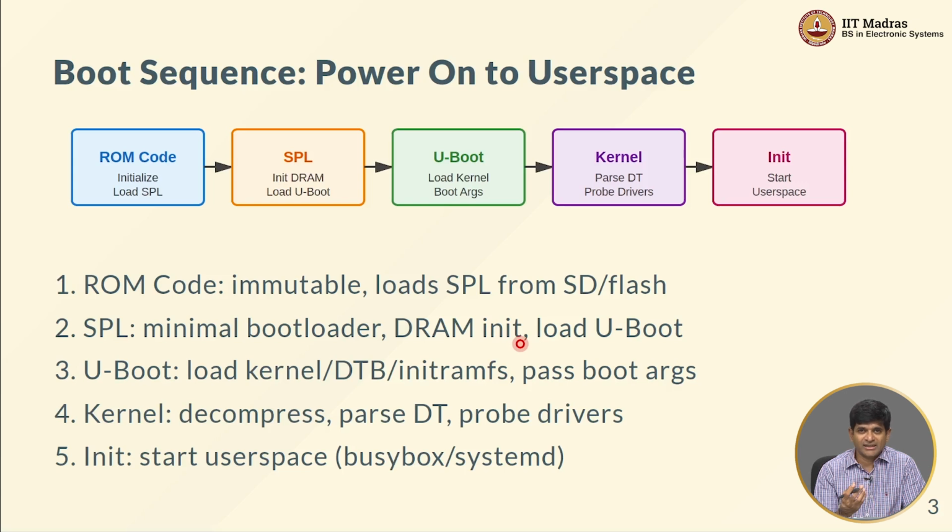There you might have seen things like the strobe sequence parameters, the various timing parameters associated with the DRAM, which need to be set up properly by writing to certain registers. If you don't do that, the DRAM is probably not going to respond the way you expect, because it has to be tuned for the specific bus and the system on which it has been connected.